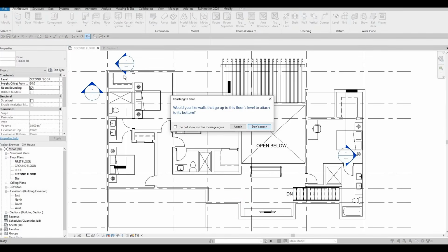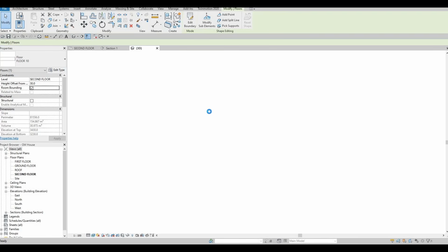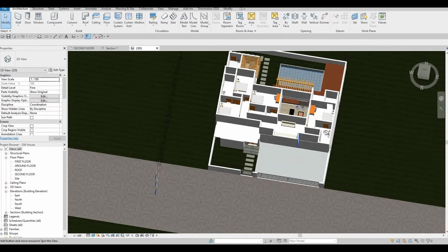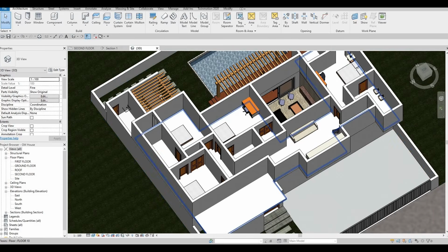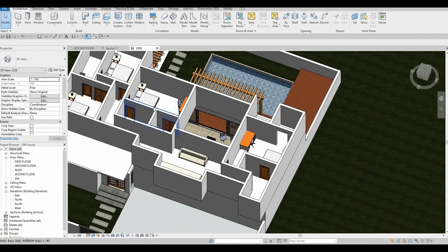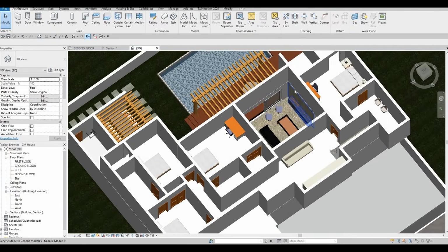So now click on finish, don't attach it, or else you will have a gap between first to second floor. So just click on that. We have the floor. We can change the floor, the one below. Usually I want it to be obviously, we could add a different flooring for the washroom by using paint. So we could do that later on if we want to.